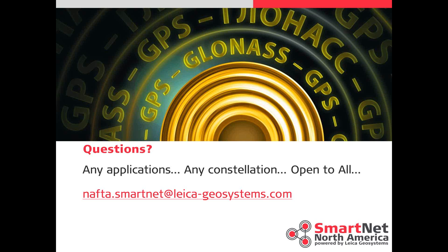RTCM IDs, yes, they're the same on Monday as they would be on Friday. If you have a question about RTCM IDs, specifically to iMAX and MAX, the RTCM IDs would not change. If you're using a different brand, Trimble, Topcon, they should be the same. We do not change our RTCM IDs without notice.